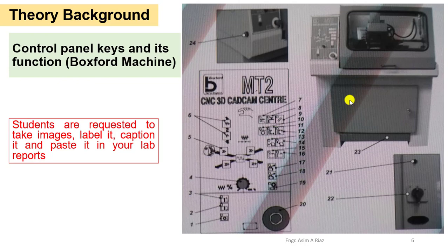X and Z are used as in the previous class, where we discussed the axes that are used in the lathe mode, as well as the axes that are used in the mill mode. In the lathe mode, we already know we have to use 2 axes, while in the mill mode we usually use 6 axes, which include 3 linear and 3 rotational or angular axes.